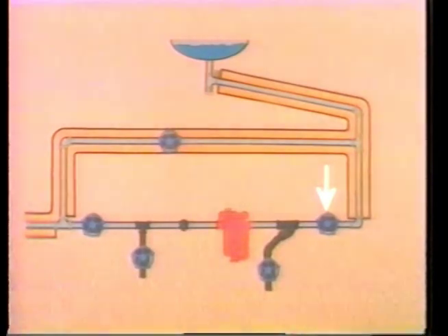or steam equipment. After the inlet valve is a strainer that removes any scale or dirt in the line. It has a blow-down valve that can be opened to clean out the strainer. The trap itself is next. Then there is a test connection with a valve. Opening the test connection allows us to see what the trap is passing.